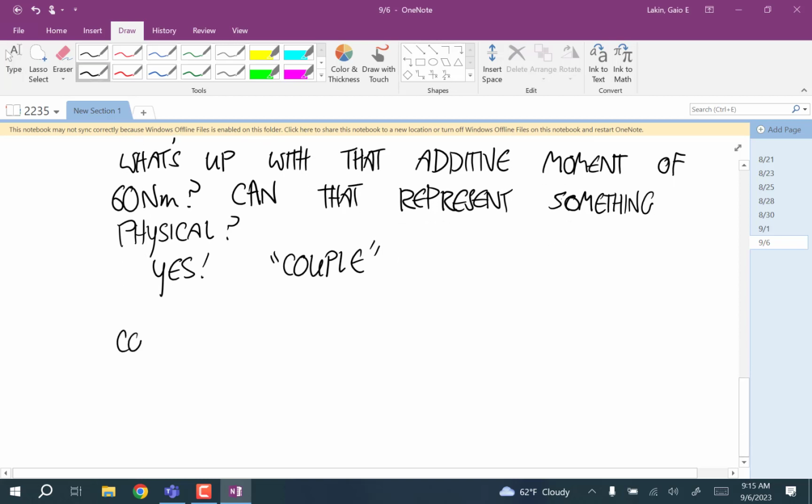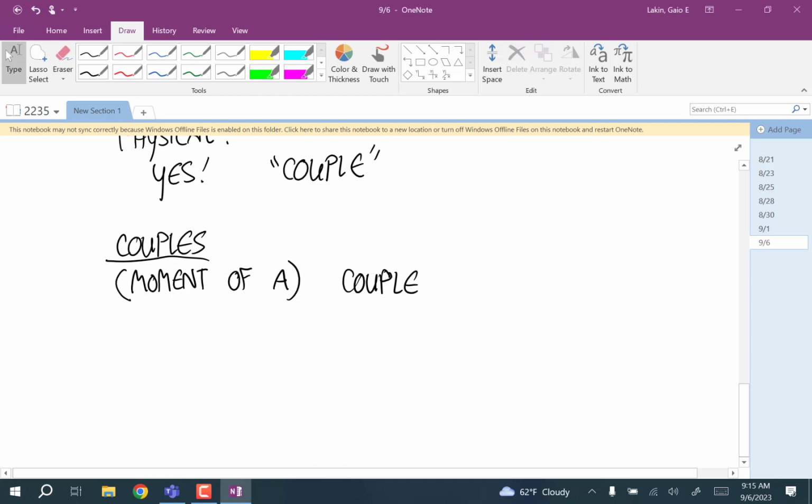Okay, so couples. Remember that couples are really the moment of a couple. People call them couples. A couple is a pair of equal and opposite forces acting at a distance from each other.